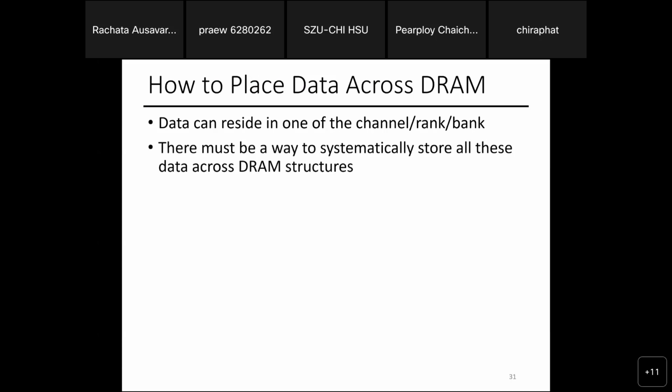If you put it at, for example, the highest address, the highest part of your address is likely to be a bunch of zeros. So then all your requests will go to bank 0. Probably not a good idea, right? Maybe you want to put it lower. If it's too low, it will coincide with the set ID. That's way too low because you go to the set ID already, you hit in the cache, right? We call this part memory mapping.